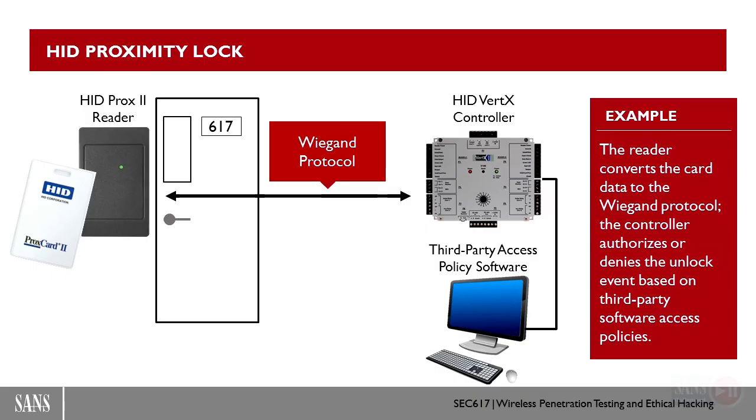No bus pirate. It's literally taking the wire and punching it down like you would a phone block, but not cutting it off. Okay. So it's just observing the changes in the electrical signal for the Wiegand protocol, and then interpreting it. So the system on a chip for either the BLE or the ESP key will do all of the watching, and it's a self-contained processor. Then it stands up a web server. You connect to it via Bluetooth or Wi-Fi, and then you're using like a web browser to interact with it. Okay. All self-contained. Neat stuff.